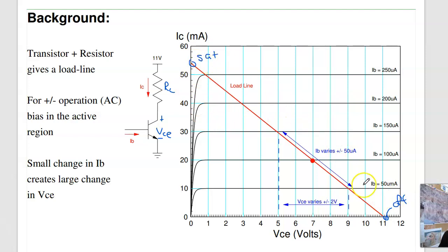The nice thing about these 2 points is the power dissipated is 0. Power is volts times amps. If the current is 0, power is 0. If the voltage is 0, power is 0. So you can use a very small transistor like the 3904 transistors, kind of small like this with 3 leads. It's not designed to dissipate any heat. That's a digital transistor designed for digital logic, designed to be used as a switch.